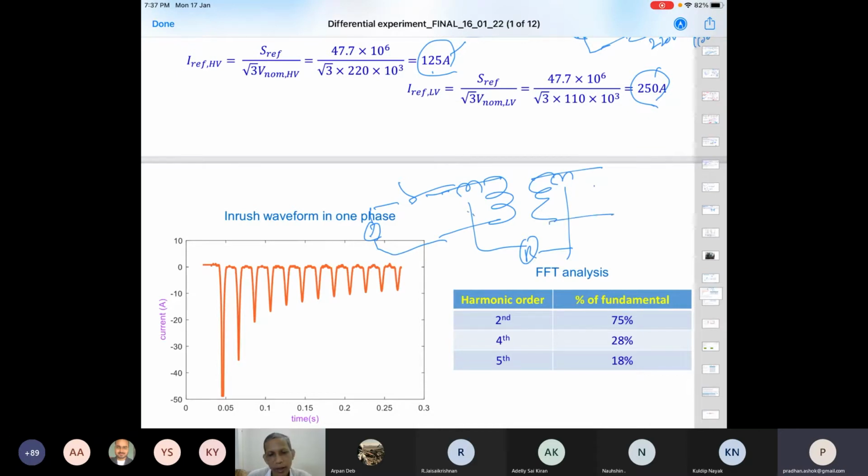When it is no load or light load condition, then if you energize the transformer, current will flow in the primary, not the magnetizing current. The magnetizing current is, as you specify, 2%, 3%. No, we are not talking about that. This is current in the primary, on the energization side, which is substantially high, 5 times, 7 times the rated current.